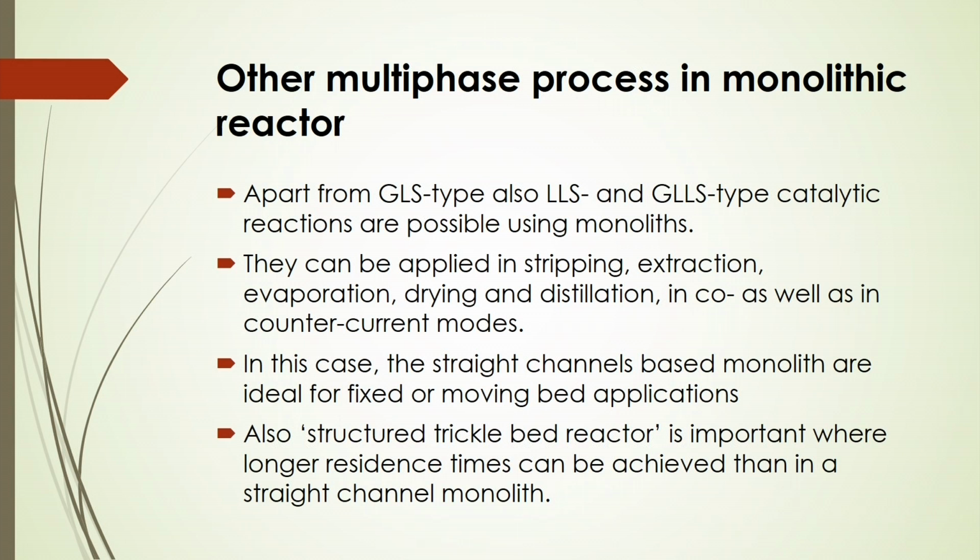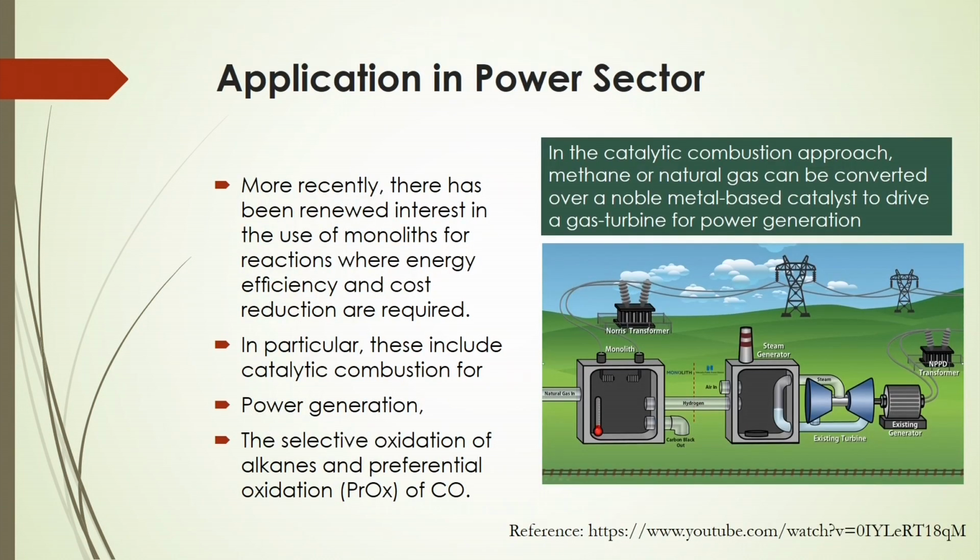In this case, straight channel based monoliths are ideal for fixed or moving bed applications, and structured trickle bed reactors are important where a longer residence time can be achieved than in a straight channel monolith. Another important application is in the power sector.